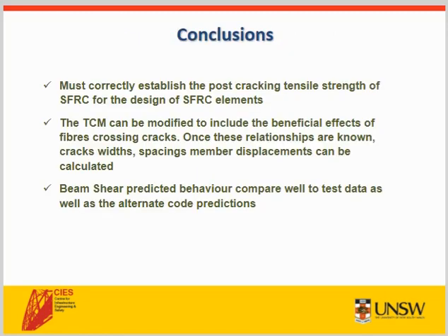To conclude, fundamentally, we must correctly establish the post-cracking residual tensile strength offered by the fibres if we're going to correctly design steel fibre reinforced concrete elements. At the elemental level, the tension chord model was successfully adapted to include the beneficial response of the fibres across cracks.